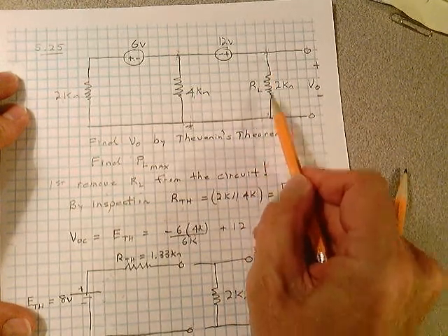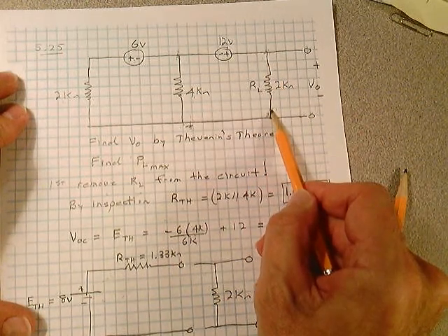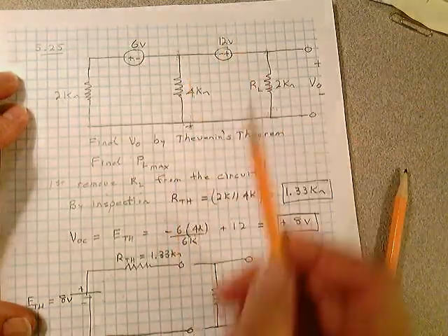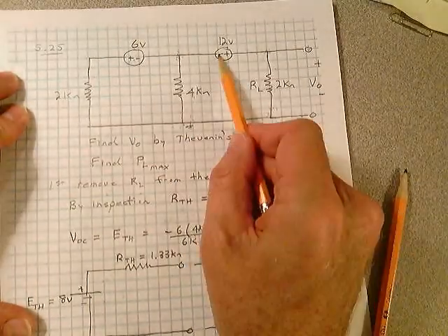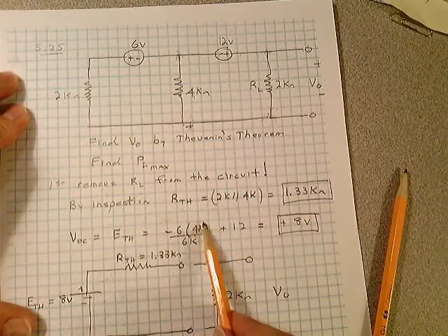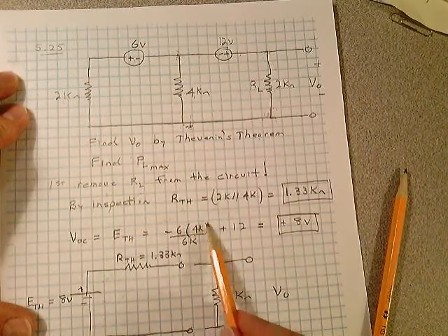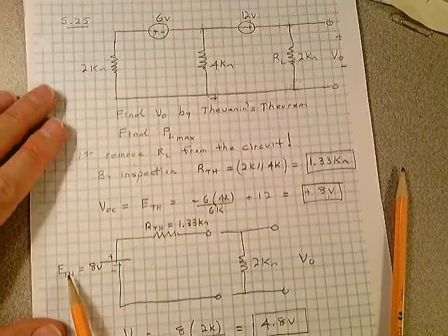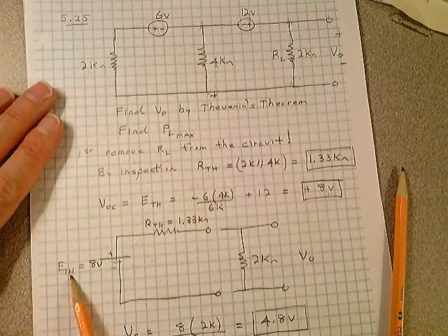This is out of the circuit. You're working a Thevenin equivalent. And if you know that voltage there, which is this, you just add 12 volts to it, minus the plus. So if that turns out to be -4 volts, plus 12, that's plus 8 volts. So you can go straight to the Thevenin equivalent. E Thevenin is 8 volts.